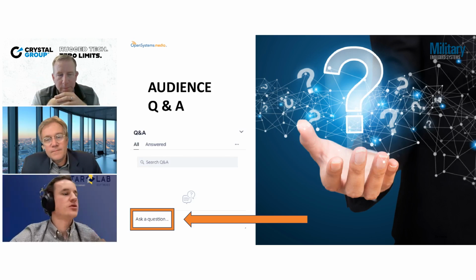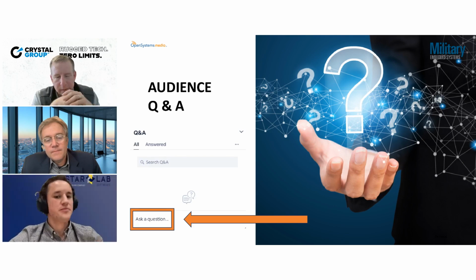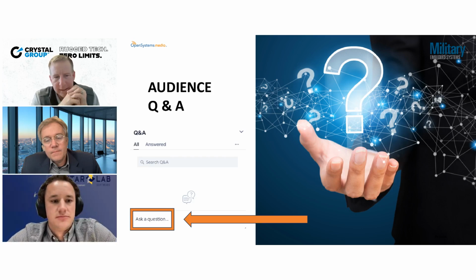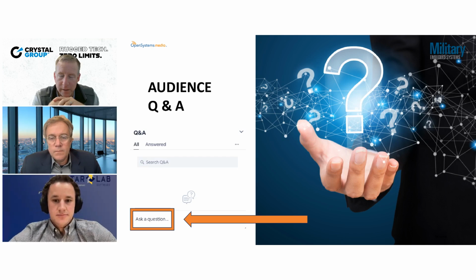The last thing, to wrap it up though, I'll say so much of this is, yeah, you can simulate and you can use good engineering practice, but ultimately the best thing to do is to put together a design and go into your in-house compliance lab and evaluate it, test it, instrument it, and figure out what works and what doesn't. Sometimes that's much faster than sitting around at a computer trying to simulate very complex and sometimes unknown geometry.